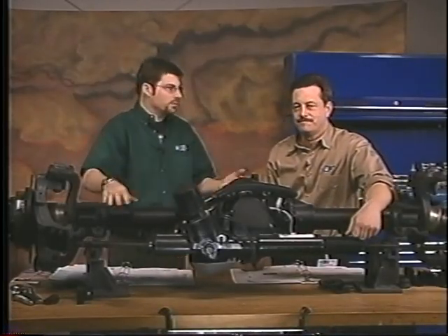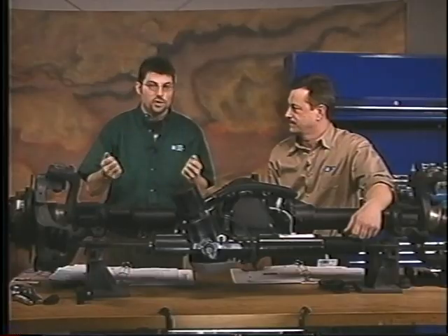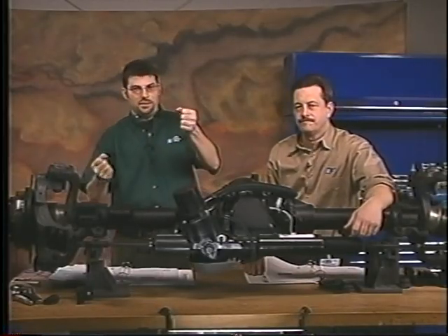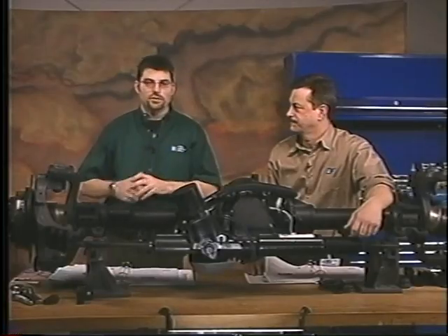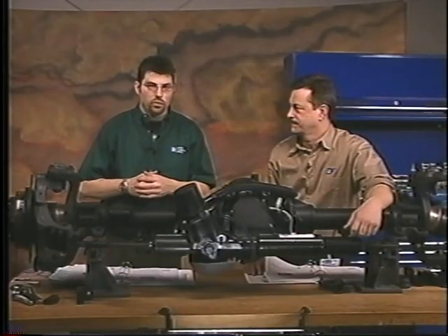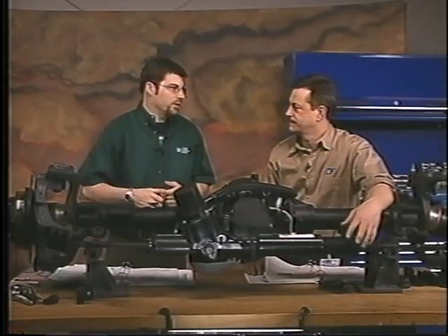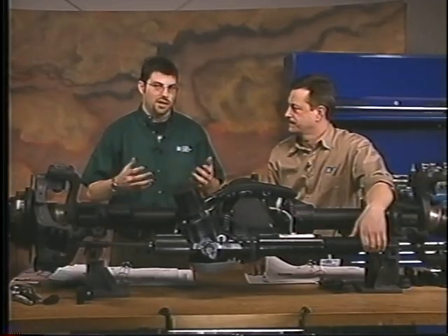Now, basically what Delphi Engineering is telling us is that when we're in the tow mode, the four-wheel steer tow mode, we may see our steering wheel offset slightly, okay? They're telling us plus or minus 5 degrees. So that's definitely an important point that you want to remember. Plus or minus 5 degrees may be off, it may not, but you should probably be aware of it in case you get a customer who comes in and thinks they have an alignment issue.